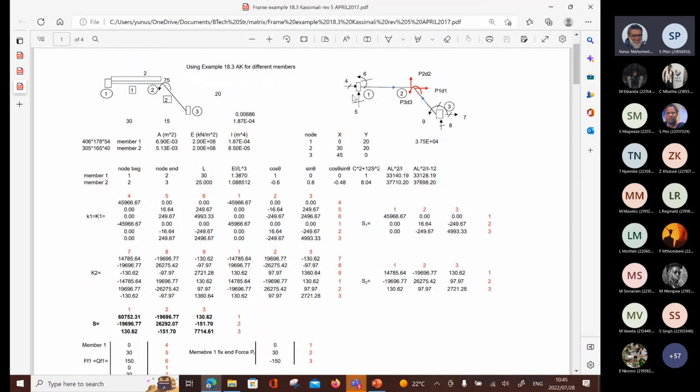So you have to look at member 1 has no degrees of freedom. Member 2 has 3, that's why it's identified as red. And node 3, sorry, has 3 reactions but no degrees of freedom. So I'm identifying the degrees of freedom in red. I'm identifying the reactions in black with hatches on them. So you can see that really all I have to first start off by getting is 3 unknowns.